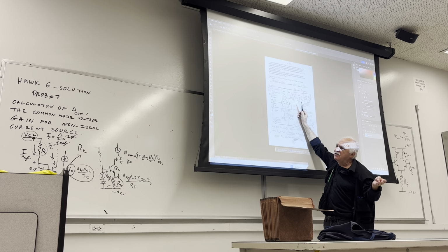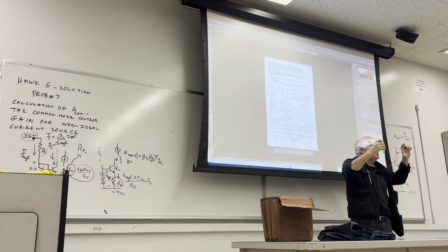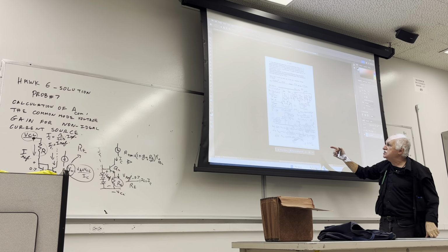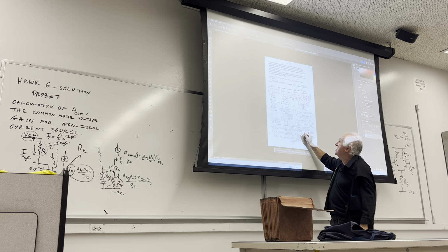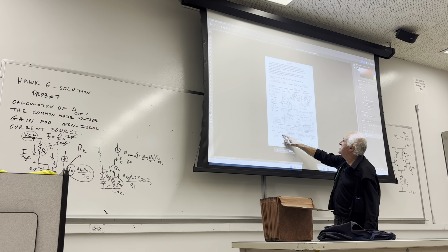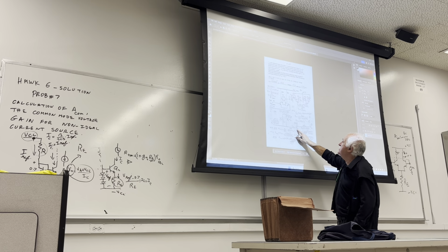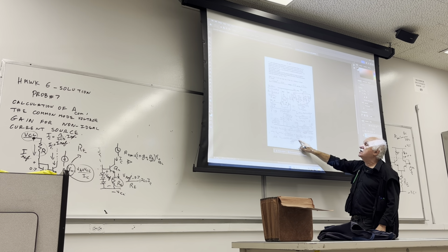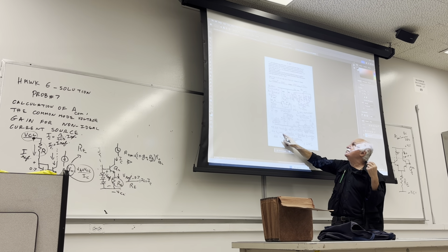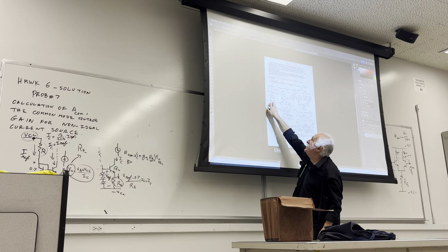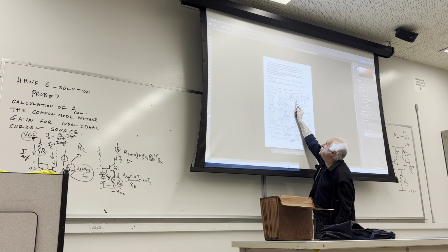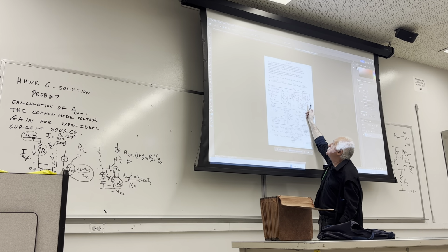So we do have an input impedance known as the common mode input impedance. That common mode input impedance is VCOM, which is this voltage, divided by ICOM. ICOM is 2IB, because there are two signal base currents moving from that load, one for transistor 1, the second for transistor 2.